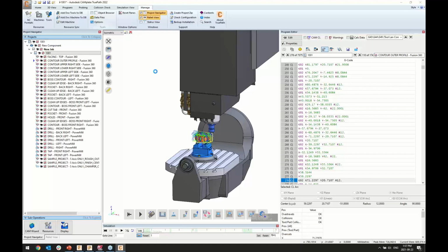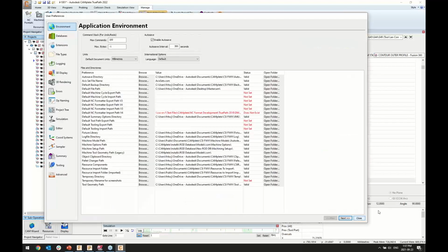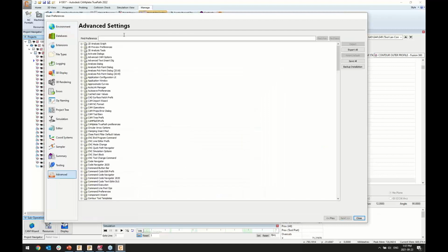So whether that would be just the part, just the fixture, or the overall extent of the toolpath, we can define the bounding elements around, let's say, the parts, and then at that point we can start optimizing the retract to not go all the way to the home position, but only clear that particular safety volume.